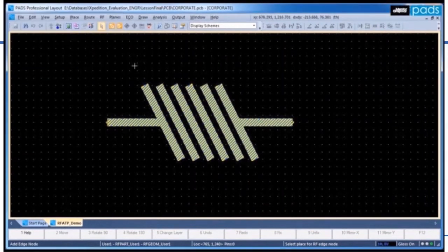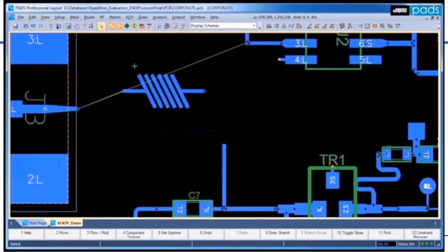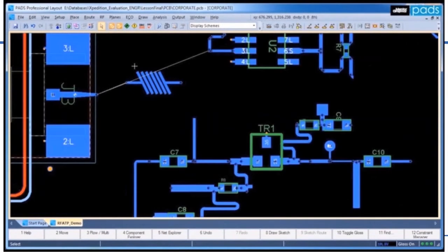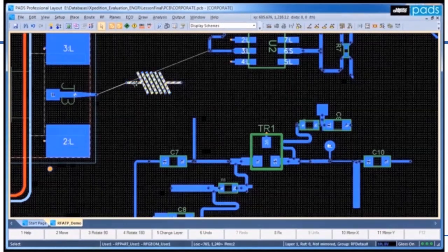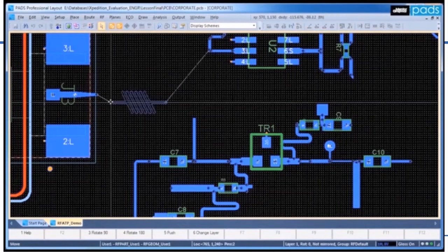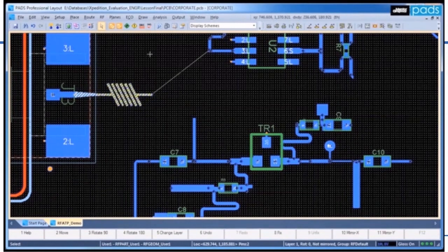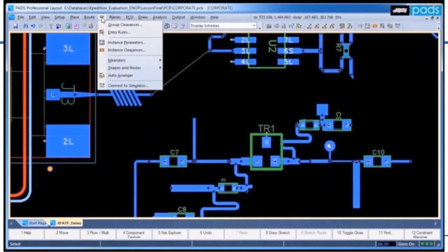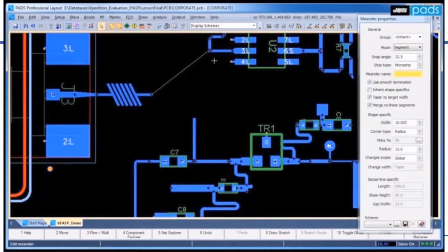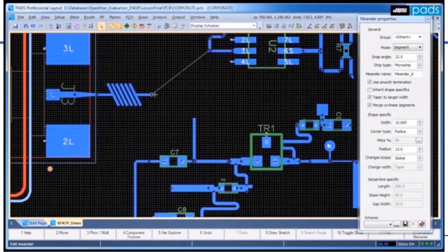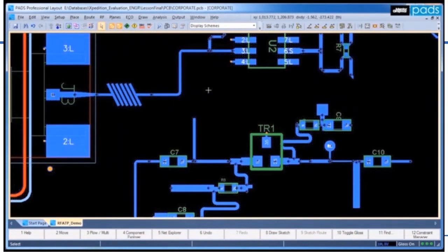correct DRC handling. It is now possible to move the RF structure as a single entity. To connect it, simply move it over a node or component pin with the same net and it will automatically snap into place. To complete the connection of a meander or RF trace, an RF trace can be added to connect the other end of the filter. The filter is now connected and DRC will correctly handle the connectivity, and the manufacturing outputs will also understand that the imported filter is now an integral part of the RF circuitry.